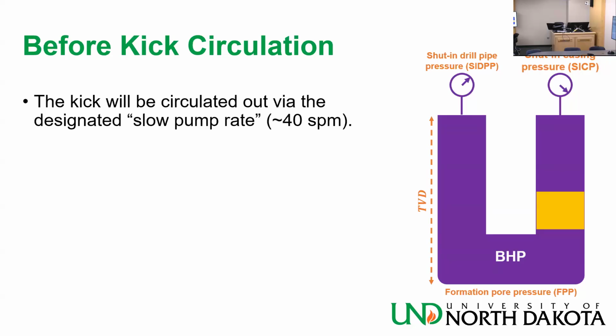That is the frictional losses throughout the pipe, the system at that rate. We did it for 40 and we did it for 100. We said we are going to be circulating out the kick at 40 and actual drilling at 100. This is why you need to know the frictional losses at that point. Always before you start drilling, you need to do that.